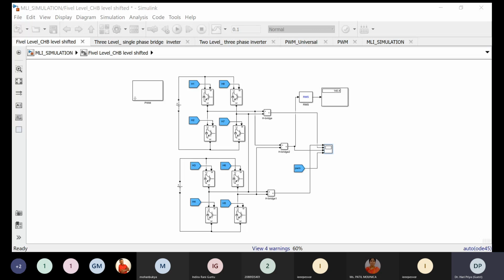Similarly, the pulses obtained from 0 to 0.5 are responsible for an output voltage band of 0 to 100. In this way, by making it a normalized form, you can exactly estimate which carrier is responsible for obtaining a specific voltage band.